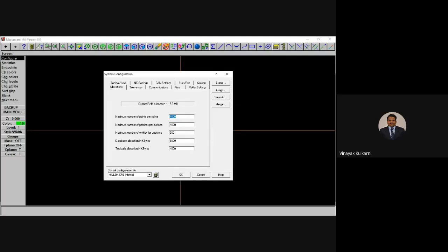So here you can see analyze, create, file, modify, xform. First, you need to set up the screen. Click on screen, then click on configure. Configure means whether you want metric units or English units. English units is basically inches. On the left hand corner of this window, system configuration, mil 8 cfg metric, it is already by default metric.